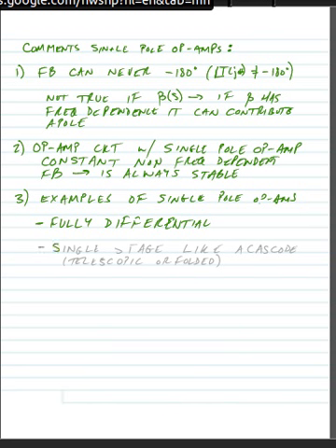Now, the other thing that we can do is use some kind of single stage op amp like a cascode. You can use a telescopic cascode or a folded cascode. Or we can just use our single stage source coupled pair with a current mirror load, and we have a pole due to the current mirror, but that pole is likely at a very high frequency, so it probably doesn't impact the stability.